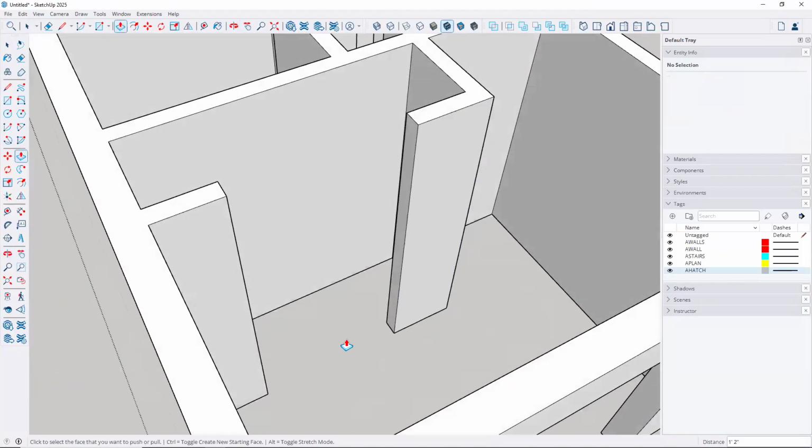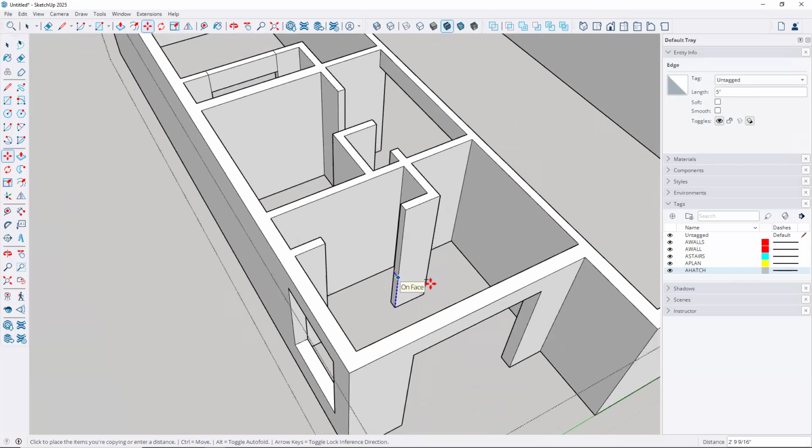I'm just using these openings as opportunities to show you some modeling techniques. So let me hit the space bar. I'm going to take this line here. I'm going to type M for move, select that endpoint, up arrow key to constrain to blue, tap control. It's going to move it straight up, and I want it to align to this endpoint here, that line, give that a click. So now I have that point.